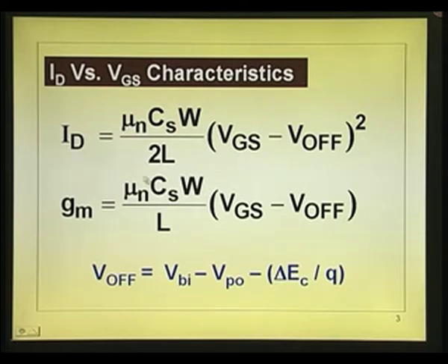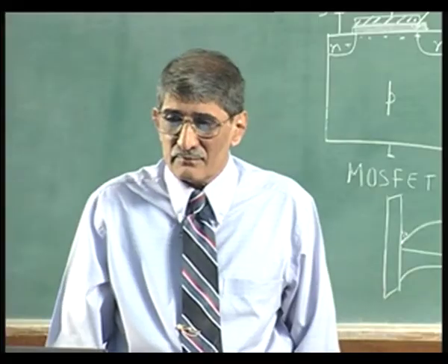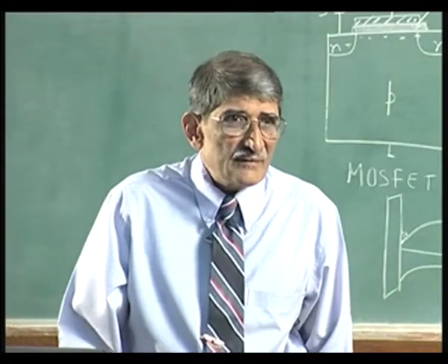Plus, that is about a factor of 8 to 9, and this is larger for the same thickness by a factor of at least 3. So, 9 into 3, 27, 25 to 30 times larger transconductance and mobility, which is fantastic, as you can imagine.